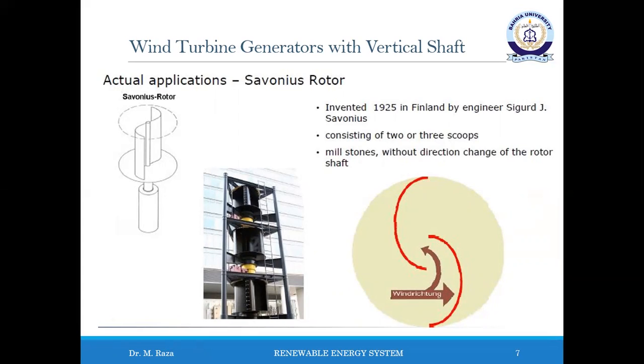Because they are drag-type devices, Savonius turbines extract much less of the wind power than other similarly sized lifting-type turbines. Much of the swept area of the Savonius rotor may be near the ground if it has a small mount without an extended post, making the overall energy extraction less effective due to the lower wind speed found at lower height.